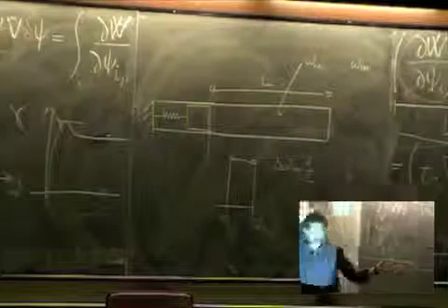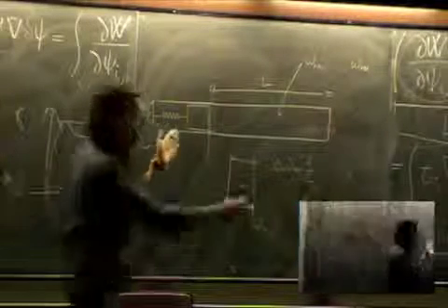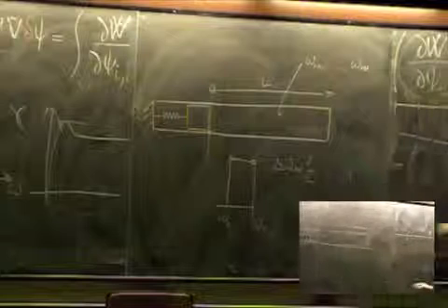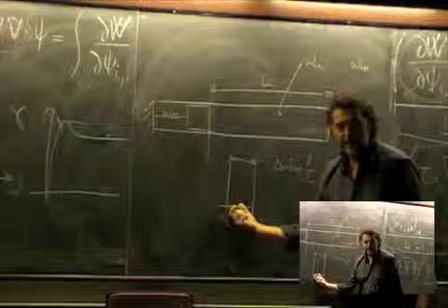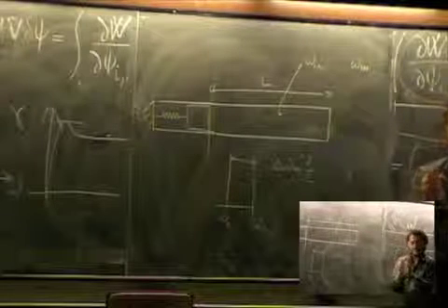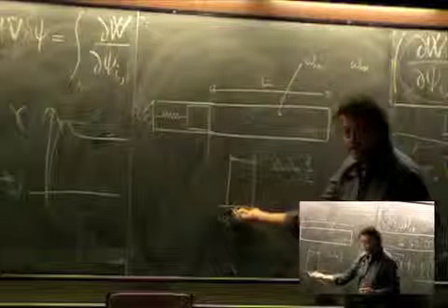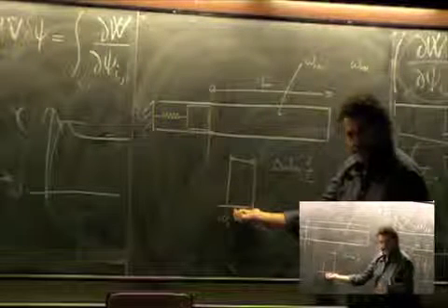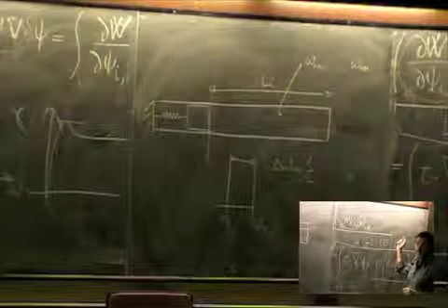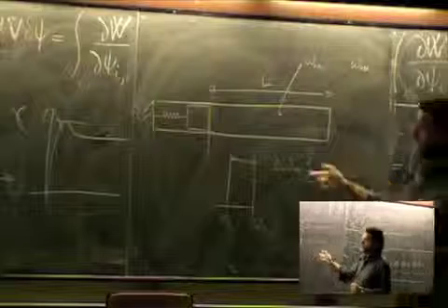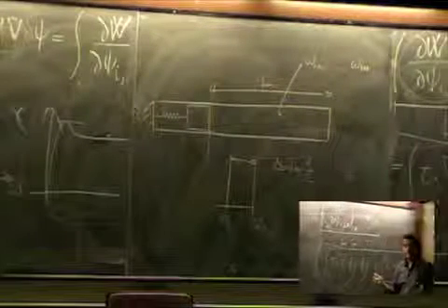It's easy to show this result. Now, if you increase the length of this pipe, the mutual distance between the eigenvalues is reduced. The longer the length, the smaller is the gap between frequencies. So if you have an infinite length for this pipe, you have not a discrete spectrum of eigenvalues, but just a continuous distribution of them.